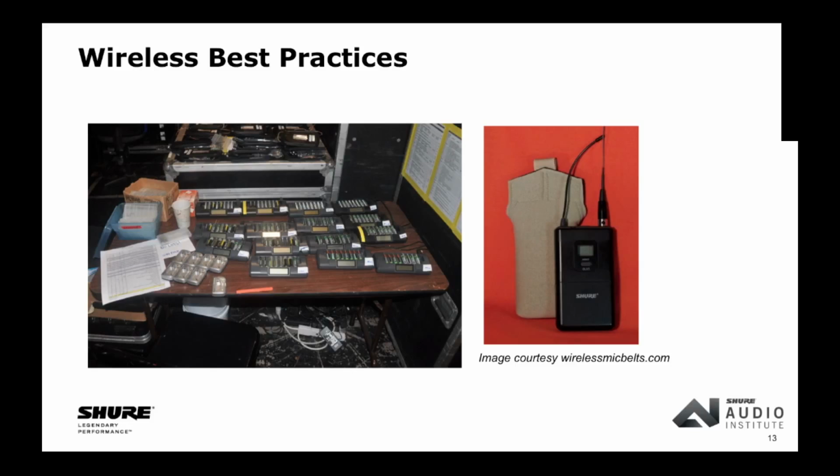You just cut two little holes in the top so the antenna and the mic element stick out. You zipper the pack in there. And generally, if we're doing that technique these days, I invert the mic pack and put it upside down. The plastic bag keeps the sweat out of the seams of the pack itself, but to keep the sweat out of the connector, when it's upside down, the sweat will roll over the connector as opposed to rolling into the connector.